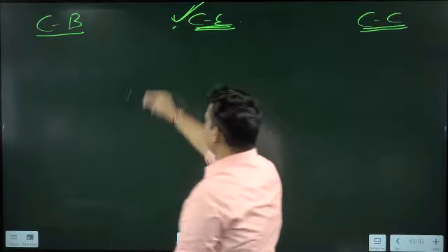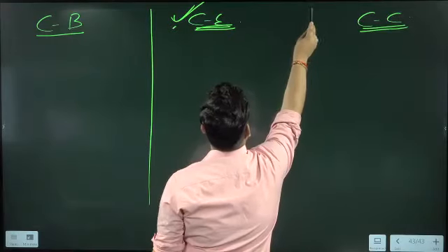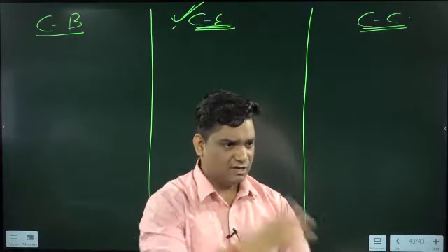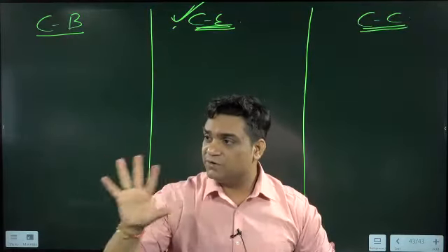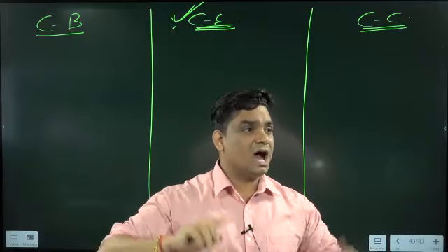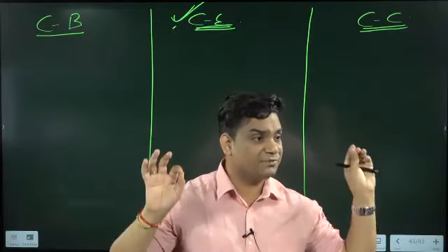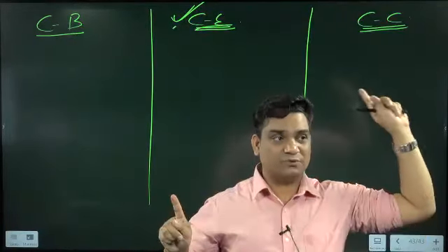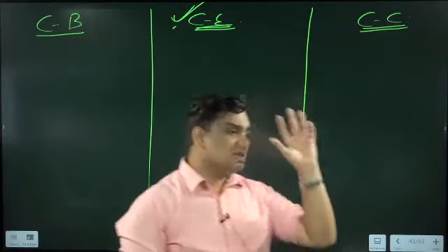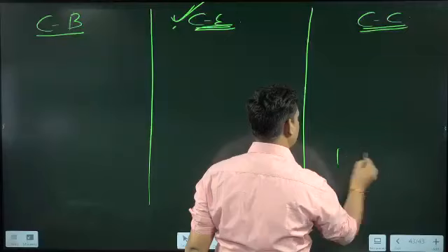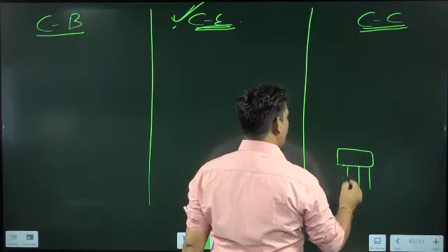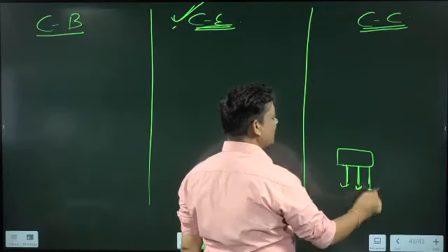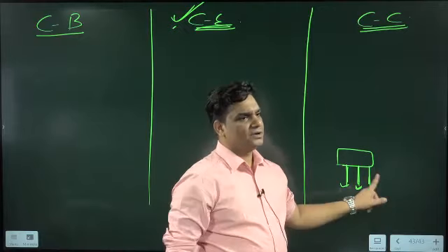Now, how to remember these formulas? Just to remember, we prefer to take input from the base and output from the collector. This is the preference: take input from the base and output from the collector if they are available. A transistor basically has 3 pins, as you can see in the physical diagram. Out of 3 pins, 1 pin is for the input, 1 pin for the output, and 1 is made grounded, constant, or common.